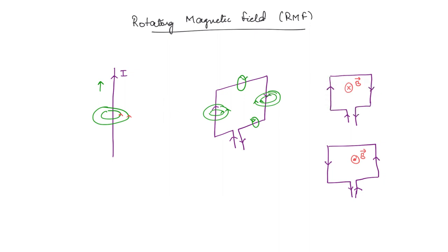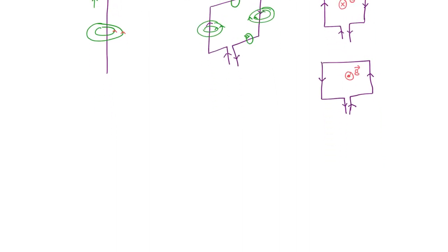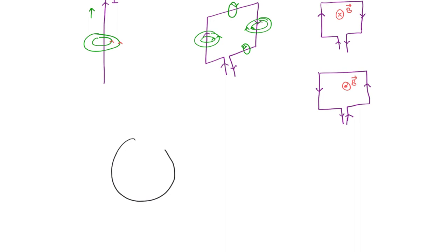So these are some of the basic concepts. Now you take a machine, the stator of a machine, and for this stator, let us take slots here. That means we can place the conductors, the coils, here. The coils we will mark with red. So this is one coil and this is the other side of the same coil. We are seeing it from this end, the top view. If the current is flowing in the upward direction on one conductor, let us take it to be outward, then on the other side the current will be going into the plane.